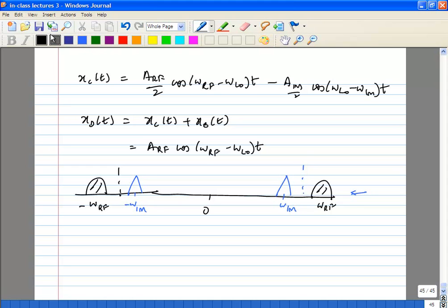Okay. So what are the major issues? Of course the major issues are you're trying to cancel something. You're relying on the fact that you have perfect 90 degrees and you're going to cancel plus and minus IM. Now what happens if you have amplitude mismatches between the two parts? And you could have phase mismatches between the two parts. Your sine and cosine may not be exactly 90 degrees. Your phase shifter may not be exactly 90 degrees.